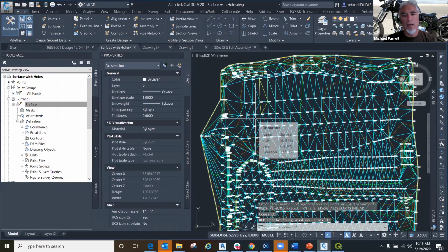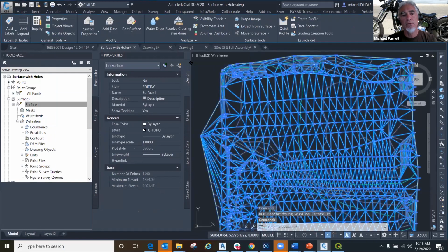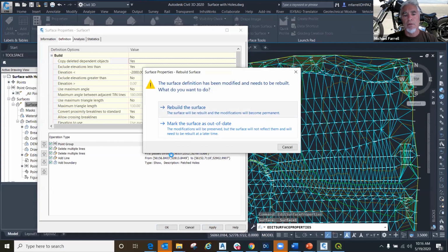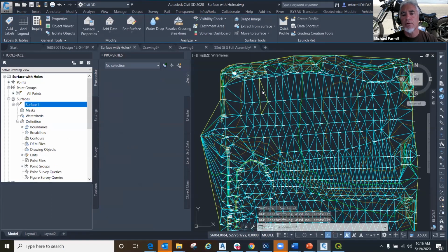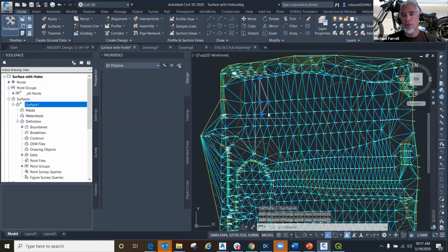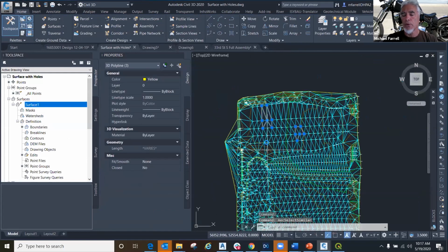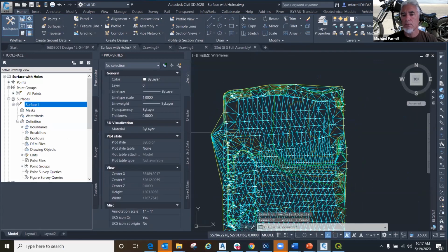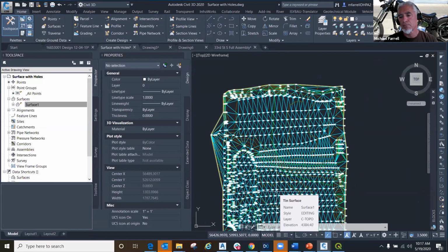So that's where setting this guy to yes can let you get rid of some of the underlying AutoCAD objects that you use when you're building a surface or editing a surface. And then the surface basically makes a copy of that data that it saves internally. So even if you delete it, it's still there for you. Okay?